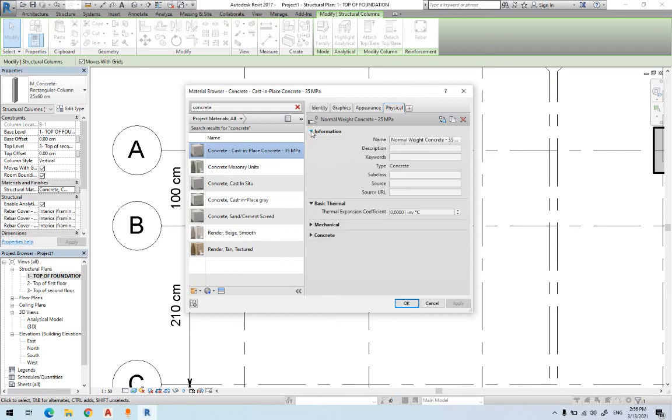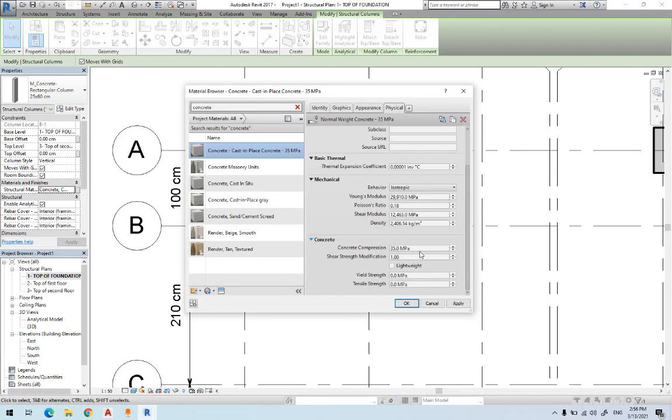We told you that Revit can be used for different purposes, not just civil engineering. I told you we use Revit to analyze the thermal exchanges, or the thermal analysis we call it, for the temperature in the buildings. Or like any other things, for the concrete that you have, you will see in the materials there the Poisson's ratio, the shear modulus, density, for example, the compressive strength, yield strength, tensile. If you have all the information, you can place it here.